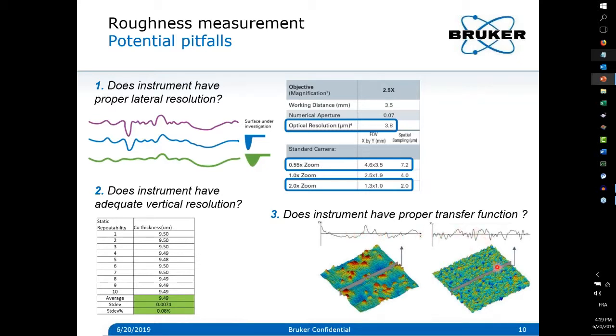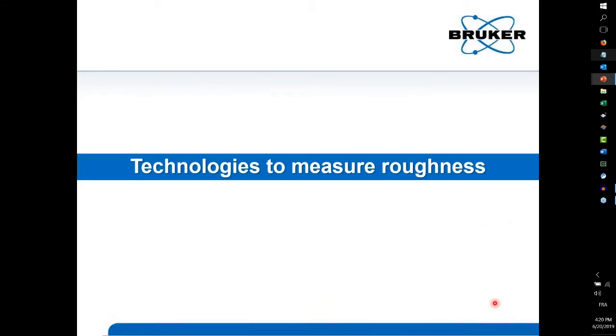So in that case, you can see how different the surface looks after seeing it through the instrument. So that's very challenging, and this is where most of the issues correlating roughness parameters with efficiency come from. If you have the right instruments, you can easily correlate. If the background noise is too high, unfortunately what you will assess every time is the system rather than the surface you want to discriminate.